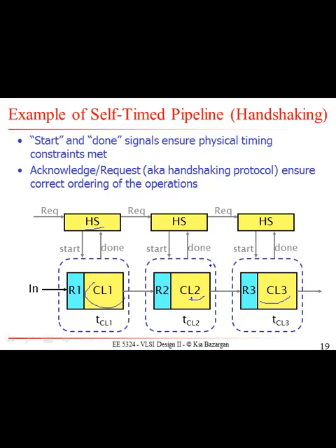And if the next unit is not going to be ready anytime soon, that means this unit is not going to accept input from its previous unit, right? So each unit has to wait for the next unit to receive its data before it can process new data. Whenever the next unit is ready to process the data, it's going to send an acknowledge signal telling them, yes, I'm okay, I received the data, you can go ahead and process a new batch of data.